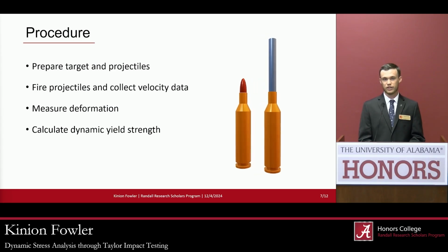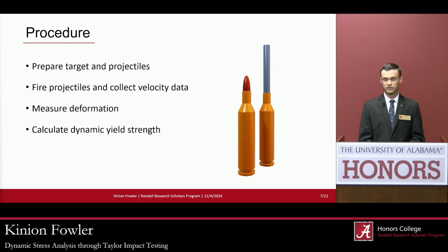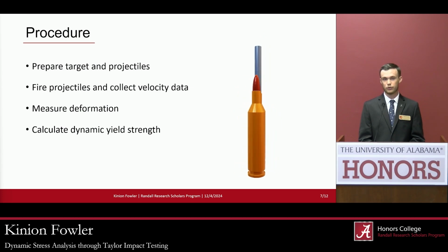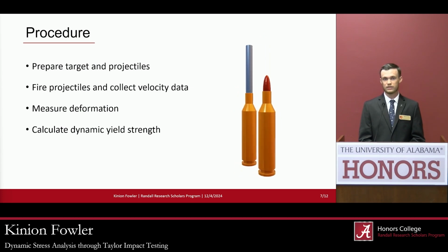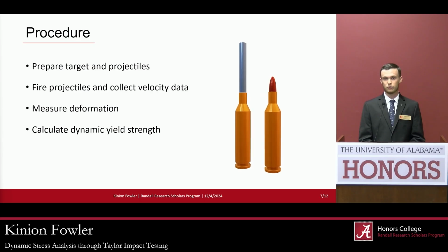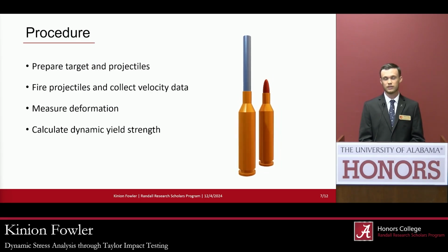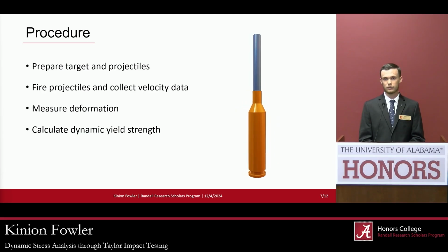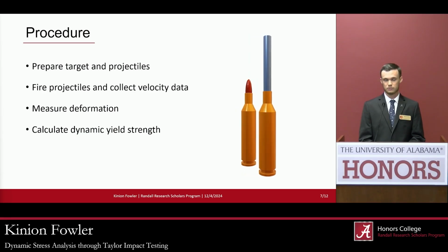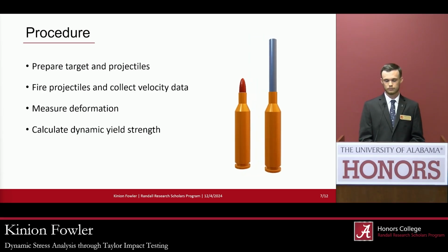We also have our projectiles that we take from a normal cartridge, such as 17 caliber, 223, or 308. The model you see is of a 17 Remington cartridge. We remove the bullet from it, adjust the powder load so that the velocity is what we need it to be, and then replace it with our milled down cylindrical samples.